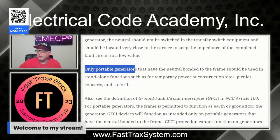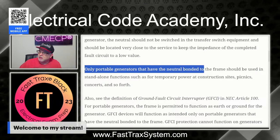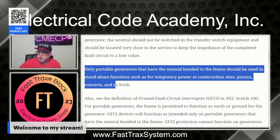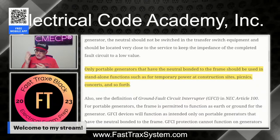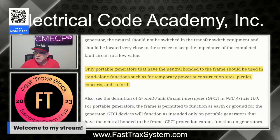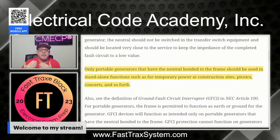Only portable generators that have a neutral bonded to the frame should be used in a standalone function such as temporary power to construction sites, picnics, concerts, and so forth. If you're buying generators for any of these applications, temporary power, construction sites, to run the job site, you want to make sure that you have one that has the neutral bonded to the frame. So you want a bonded generator. If you take anything away from this, that's what you want.